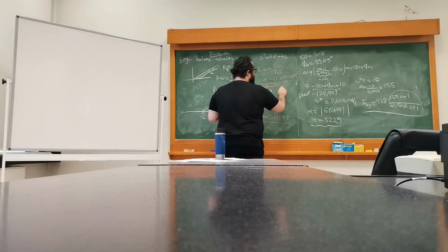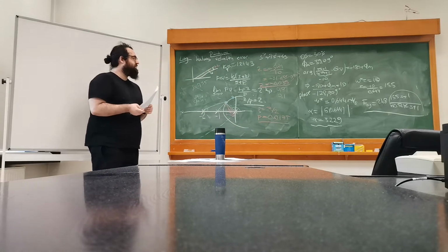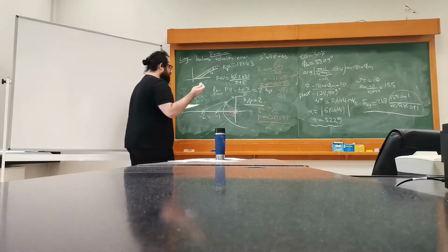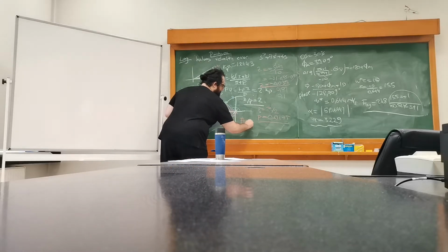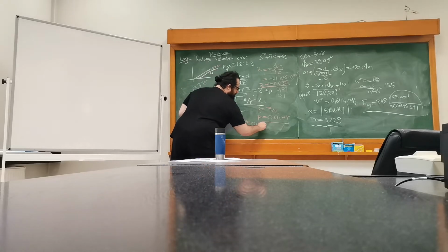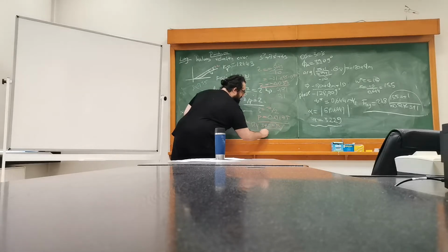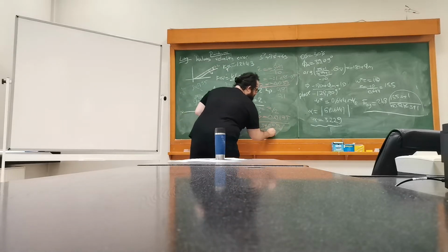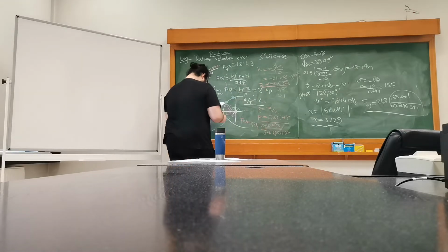You can just have 0.01, 0.1 even, they all work. Then just half of that should be p, and you're good to go. So one of the controllers that I can choose here is basically 1.24 gain, s plus 0.035, divided by s plus 0.0175. So that's basically it.